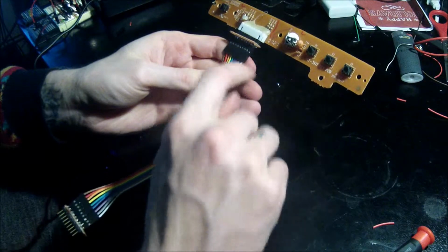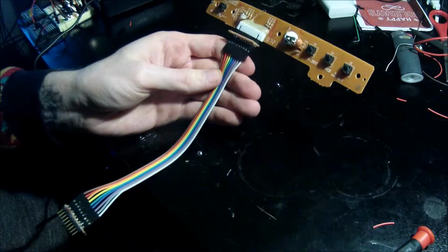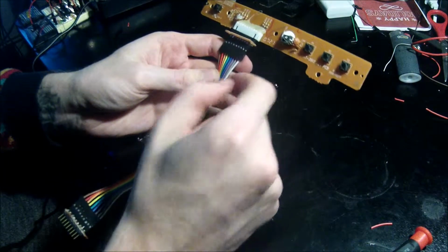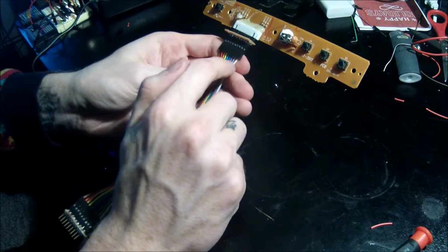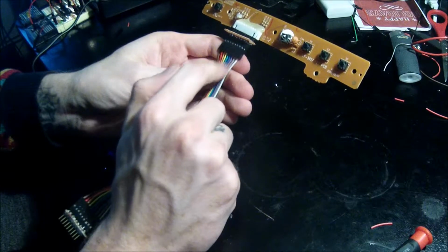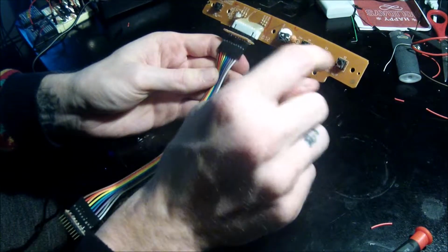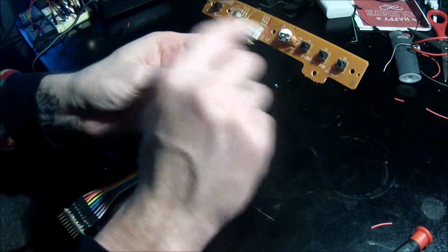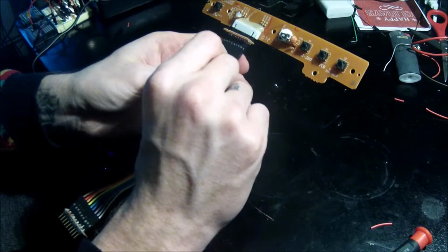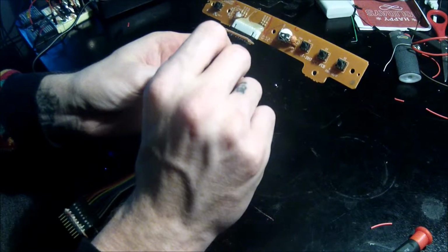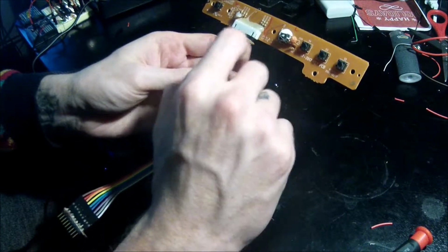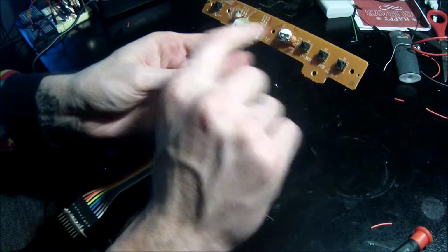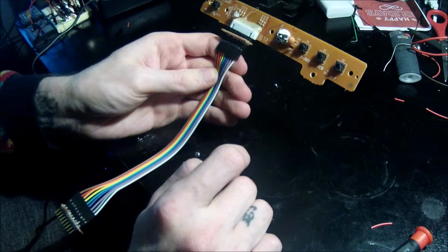What I can do now, this is a 5-volt board. I checked when it was in the amp still, and these are ground side switches. So this rightmost pin here is VCC, and the one next to it's ground, and the rest of these I haven't mapped yet. What I'm going to do is figure out which wire on this harness goes to which switch, and then splice into that and run it over to a pin of the Arduino, or of the Atmega 328 chip, and then all I need to do is ground those pins to actuate the switch circuit.